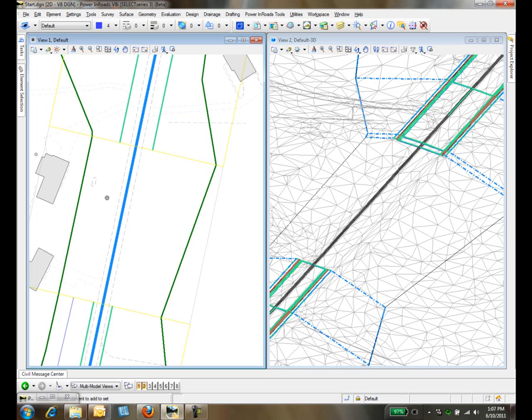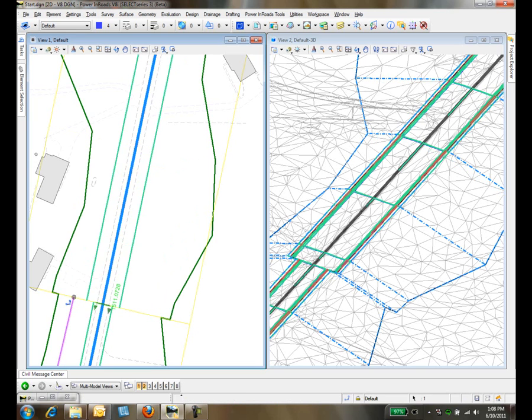So to do this, the first thing I'm going to do, notice at this point I've just got a big hole here. And I could go in and do a few things, but I'm just going to show you one way to do it. So the first thing I'm going to do is I'm going to fill the hole. So to do that, I'm just going to grab this particular template drop. I could go the other way, and I'm going to come down here, and I'm going to also snap to my wall right there. So when I do that, you'll notice it moves that one up, and it catches it right here, which is exactly what we want to do.